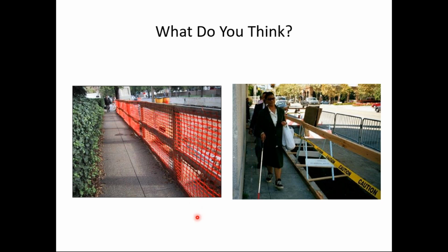So you'd want to make sure, if you use this arrangement, or if one of your contractors does, that somebody's checking to make sure that it stays taut to reduce the likelihood of a cane getting tangled up in the netting. But this, to me, is kind of good. These can probably be reused on other projects around the city or the area, and it appears from what we see to comply with the requirements for edging.